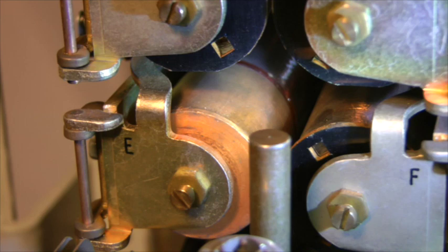When the E relay winding is energized, a magnetic field begins to grow around its coil. The changing strength of this field induces a magnetic field around the copper slug, such that its polarity opposes the polarity of the field around the relay coil, slowing down the rate of its increasing flux, thus delaying the relay operation. E operated transfers the stepping activity from vertical to rotary and de-energizes the vertical magnet.